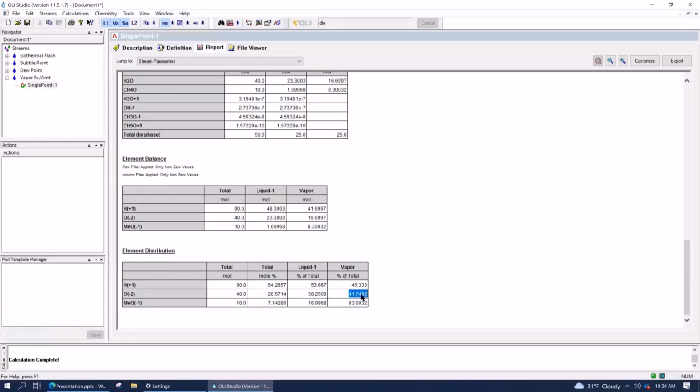In other words, we have a way of separating this through distillation. So if I start putting multiple stages together, I can separate methanol from water until, if there's an azeotrope, we get to an azeotrope. I'm not sure if there's a methanol water azeotrope. Let me stop there. I went much faster here because you already understand the basic mechanics. Now what I'm focusing on is what the software is telling us in the calculation. Any questions about this type of vapor fraction or vapor amount calculation?